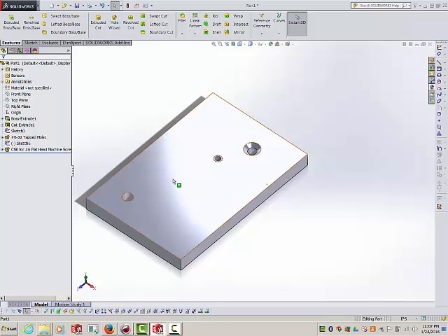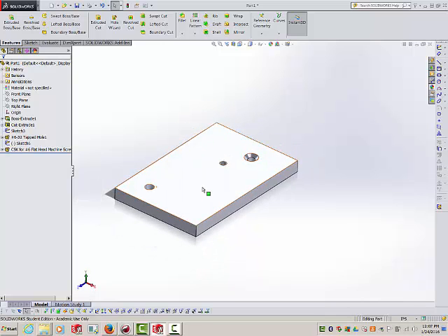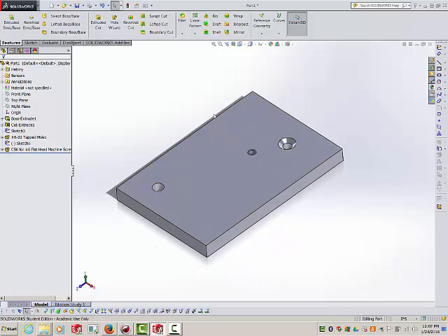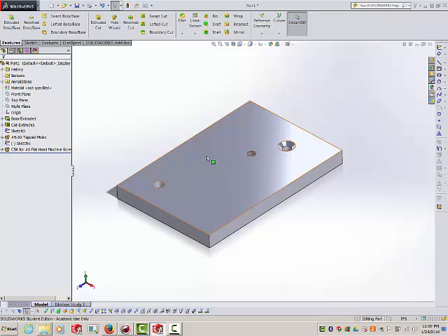Okay, so again, the workflow is grab your hole wizard, configure it the way you wanted, hit that 3D sketch thing, select the point that you've pre-created or make one on the fly, which is also possible. I like to make my point beforehand just so I know where it is and have it configured. And then drag your hole in there and you got it.